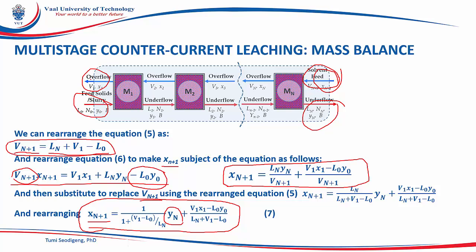If this case occurs, then the solids in the lower numbered stages, like from 1 upwards, where these solids are entrained with the solution that has higher concentration of solute, are likely to retain more solution than the solids in the stages with dilute solute concentration, which is the solids on the high numbered streams or the high numbered stages.